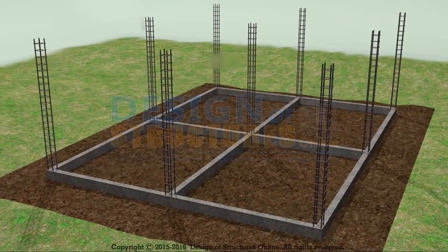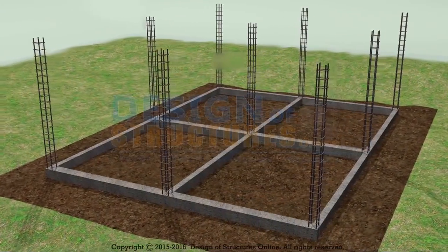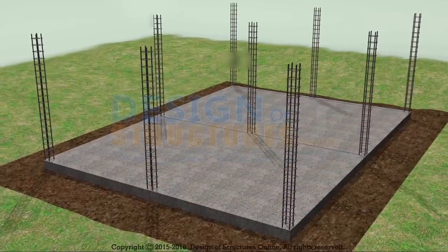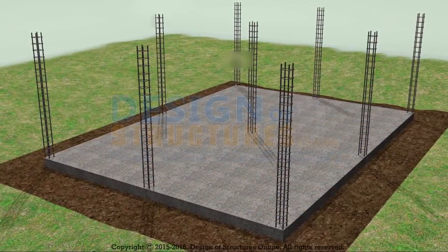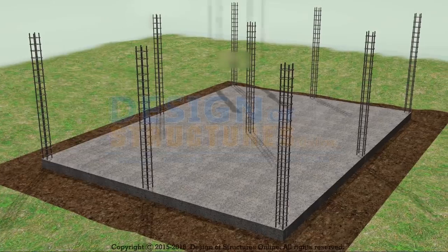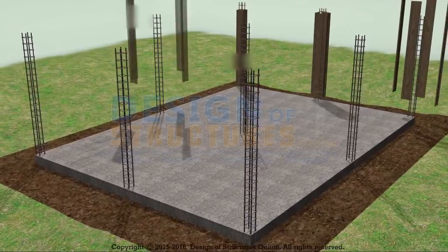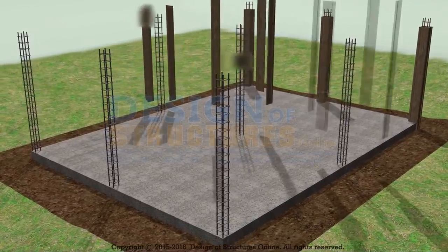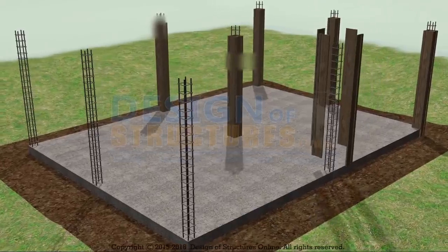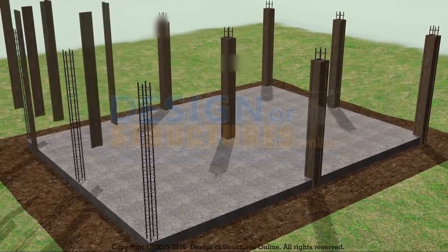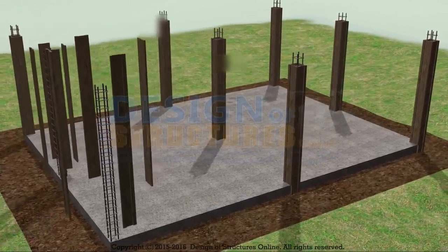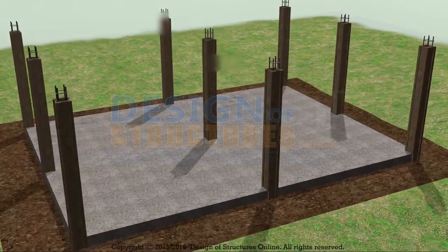Slab concreting. Grade slab requires no reinforcement as it is resting on the ground strata itself. Top of plinth beams and grade slab should be at the same level. Column shuttering. Column shuttering should be rigidly constructed and efficiently propped and braced both horizontally and vertically, so as to retain its shape. The shuttering should be set accurately to the desired line and levels and should have a plane surface.